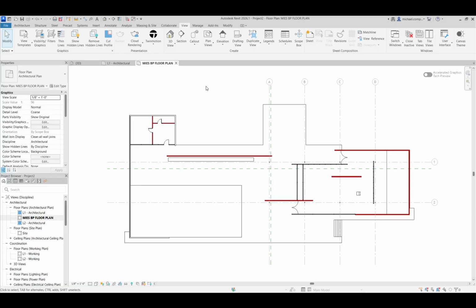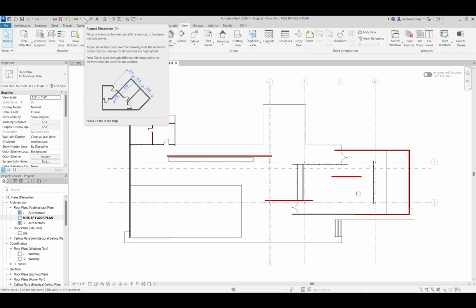And so what I'm going to convey to you is what I believe to be best practices for dimensioning. Every architect has what they think is the best way of doing it. And in truth, the people who should probably be telling us are the contractors, since they're the ones building from our dimensions. But here's what I have always been taught, and this is what I do. I start with the largest dimension and make that the furthest away. And then as elements become closer together, the dimension string becomes closer.